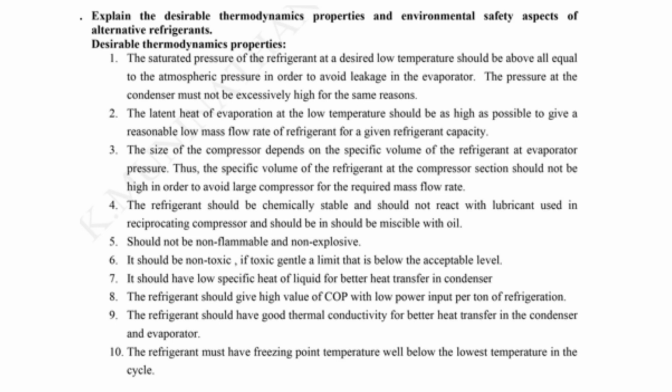The refrigerant should be chemically stable and should not react with the lubricant used in the reciprocating compressor, and should be miscible with oil. It should be non-flammable and non-explosive. It should be non-toxic; if toxic, it should be kept to a limit that is below the acceptable value. It should have a low specific heat of liquid for better heat transfer in the condenser.